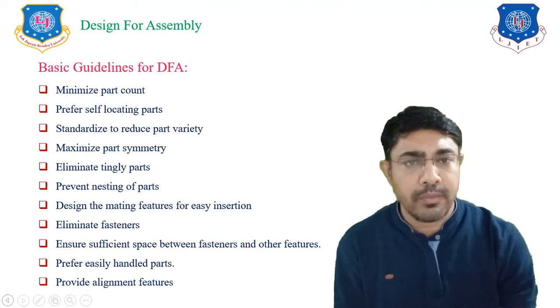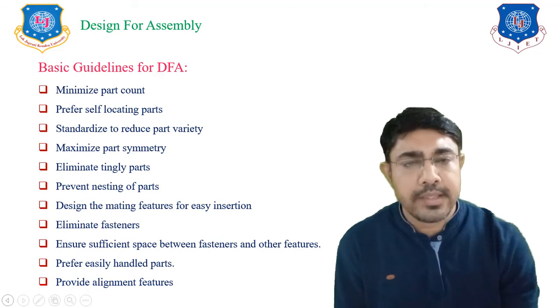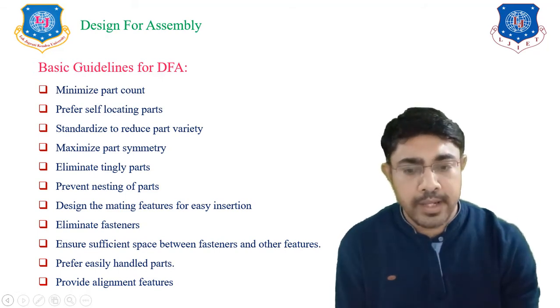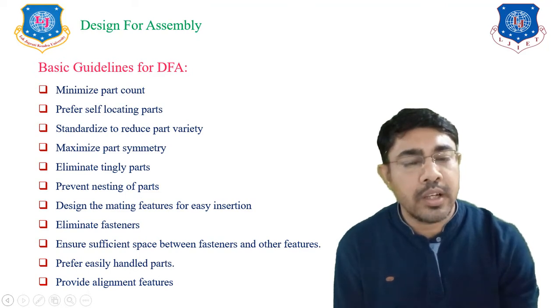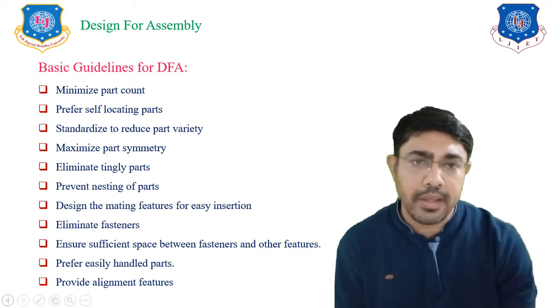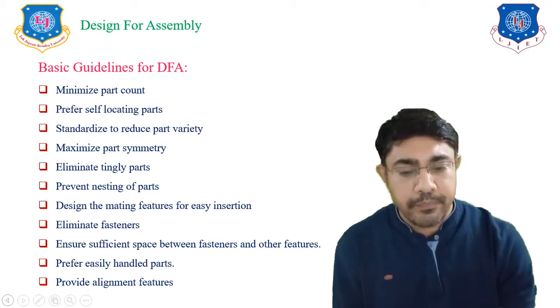As the number of parts is less, we can make simple assemblies. Second is prefer self-locating parts. Third is use standardized parts to reduce part varieties.